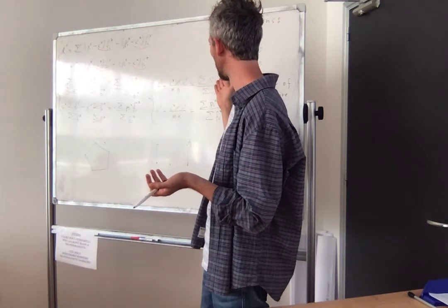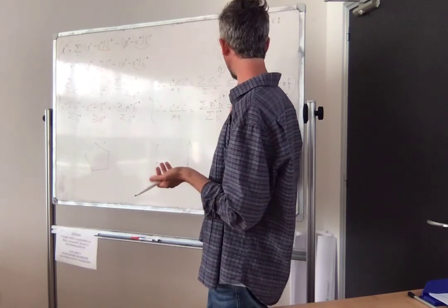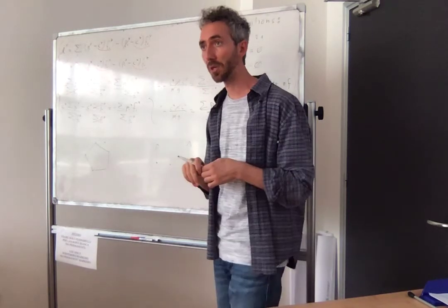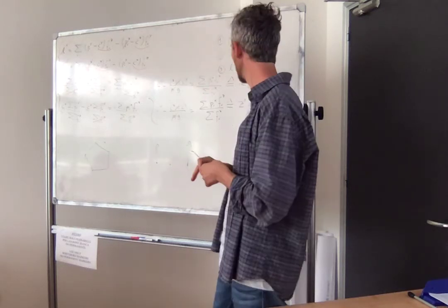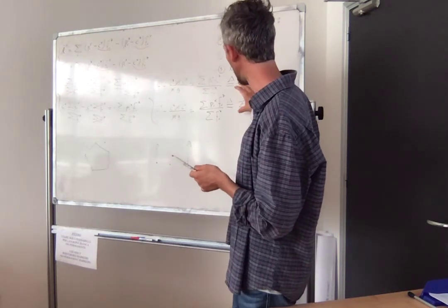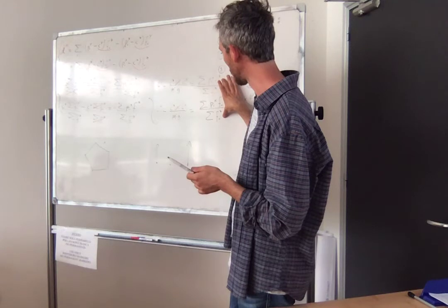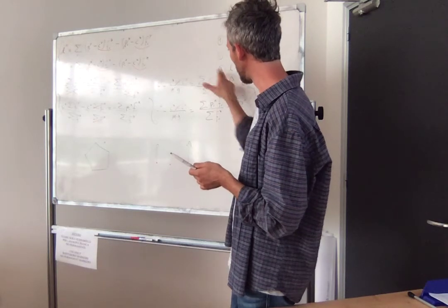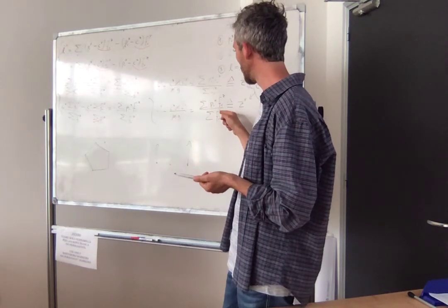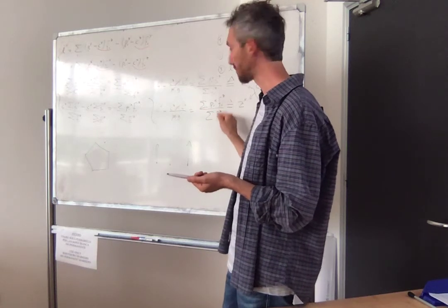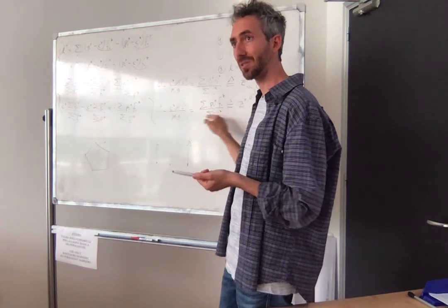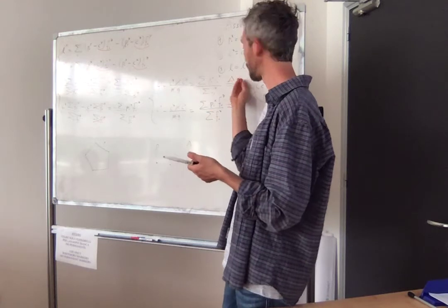So these two constraints are the same constraint but represented in different spaces. One is in the space of contact forces, the other one is in the space of the center of pressure. So I can stop using the contact forces as my control variable, because I can see here that the only thing that matters is not the single contact forces, but it's the global center of pressure.